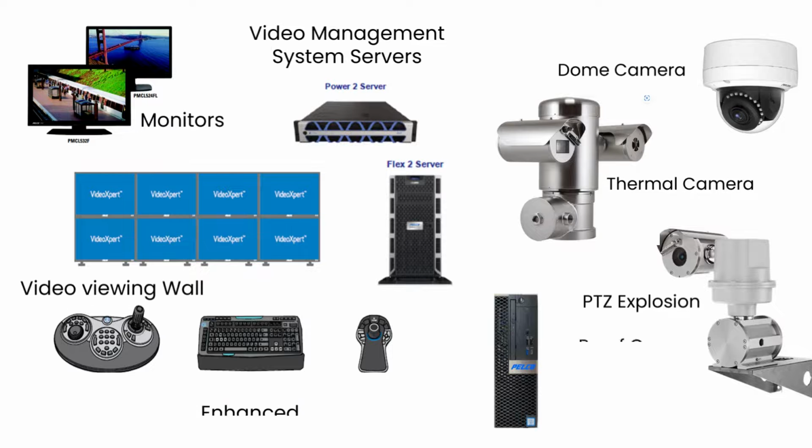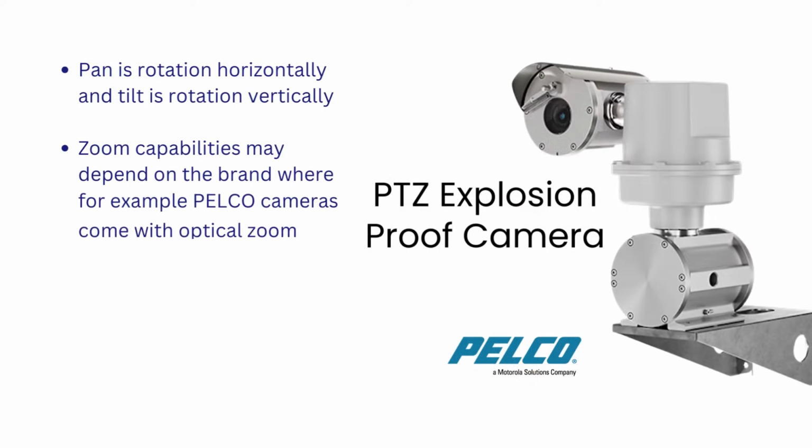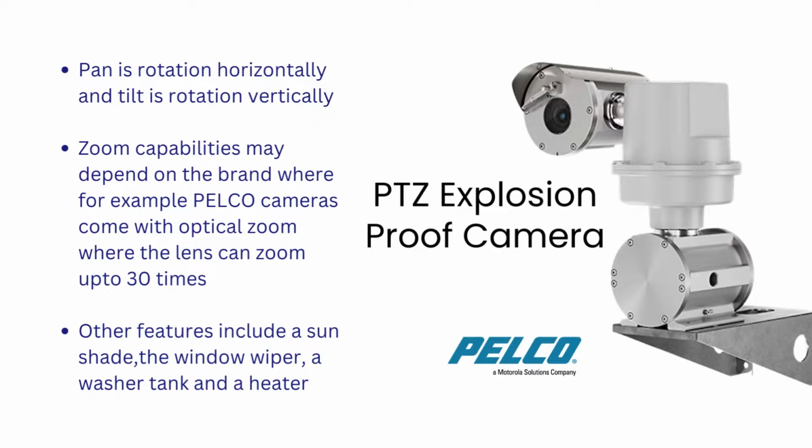We now take a look at the main components of a CCTV system. One of the most important is the explosion-proof camera. This camera has many versions, including the PTZ, or pan, tilt, zoom. Pan is rotation horizontally and tilt is rotation vertically. Zoom capabilities may depend on the brand, where for example PELCO cameras come with optical zoom where the lens can zoom up to 30 times. There is also digital zoom where using image processing it is possible to zoom even more.